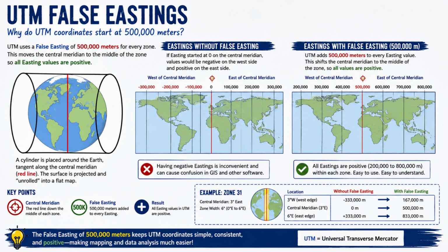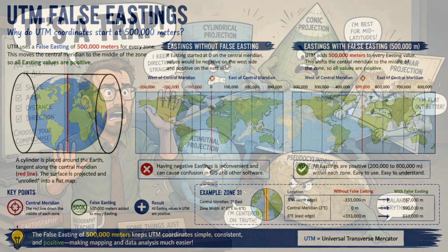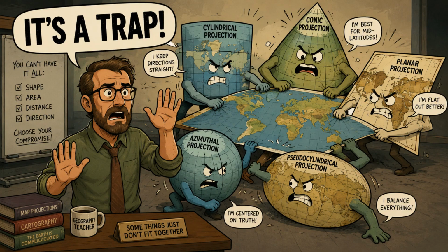Precisely. But knowing which projection to use isn't just an academic exercise to pass Section 103. Right, it has real-world consequences. Relying on the default projections in modern mapping software can entirely ruin a project, which brings us to the trap of Web Mercator. Web Mercator. It is the default projection for almost all major online map providers, right?